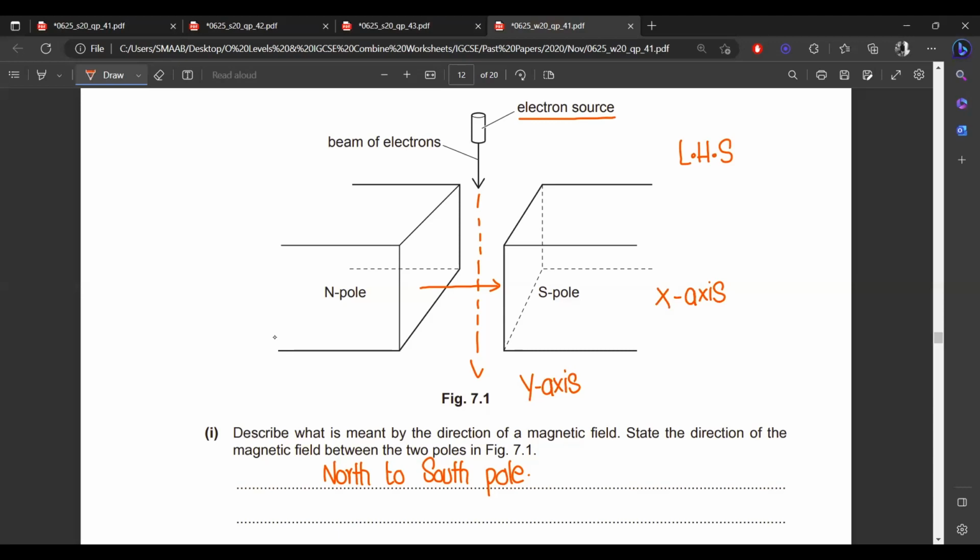Actually, we studied that current will always flow from positive to negative. So this is the positive side, and this is the negative side. So use the basic concept. Place your second finger in the direction of electric current, that is positive to negative. So that will reverse your direction into the page, right?